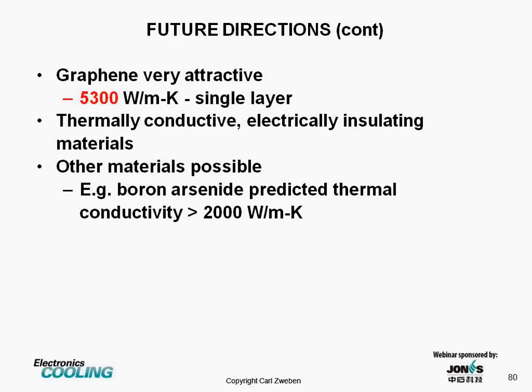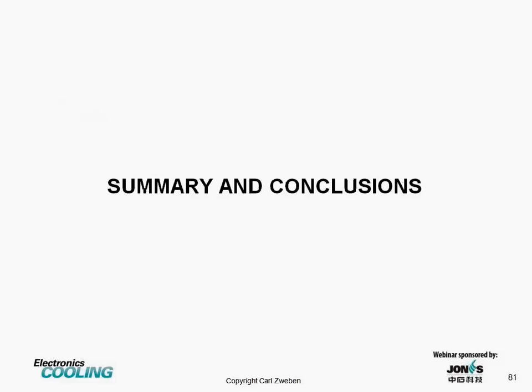I think graphene in particular is very attractive. The thermal conductivity of 5,300 in a single layer certainly makes this an interesting material to look at. We do need thermally conductive electrically insulating materials. I think in time we will see those as well. And other new materials are possible. For example, there was a recent paper that predicts the thermal conductivity of boron arsenide as being greater than 2,000 watts per meter Kelvin.